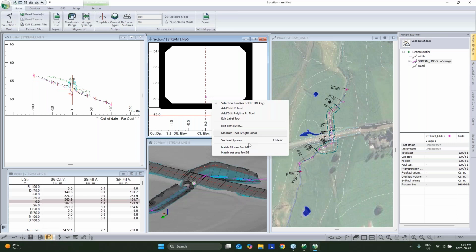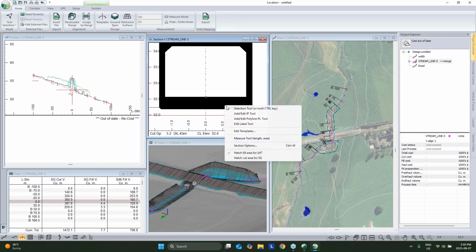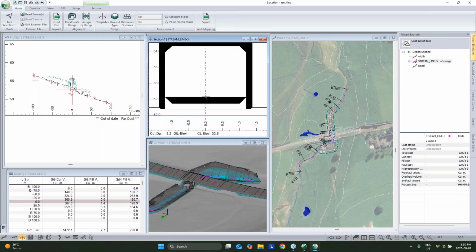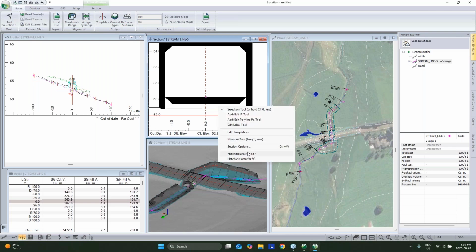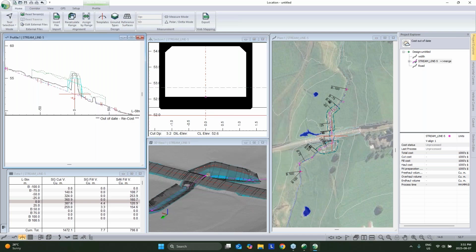Yeah, so I didn't go with a bottomless culvert. I've got an embedded box culvert with a simulated stream in here. So that's my surface 9, and we'll turn that off. I've got that material added in there with my 4% grade, and we're regrading it back to help return it closer to the natural gradient from before the previous structure was there. And the pipe is a much larger structure than what was originally there.